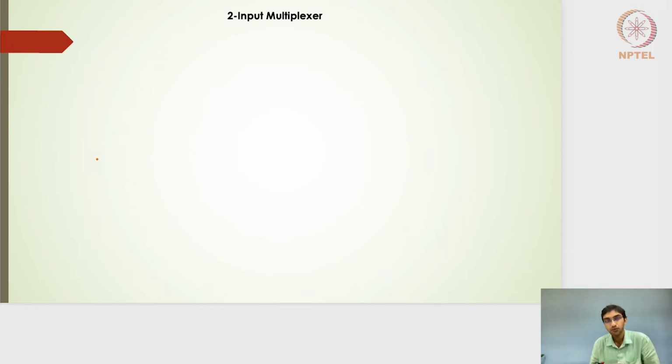Moving on, tri-state is very useful for designing multiplexer circuits, and one of the reasons is that tri-state is very simple to implement. You are going to have a mirror topology. Whatever is implemented on the NMOS pull down side gets implemented on the PMOS pull up side. That is one advantage.